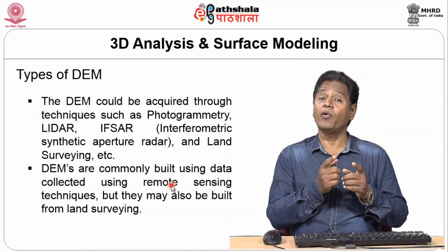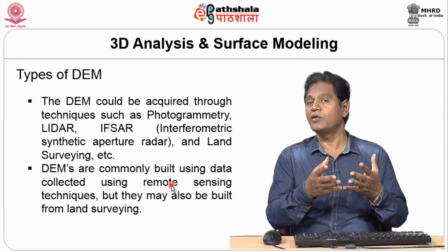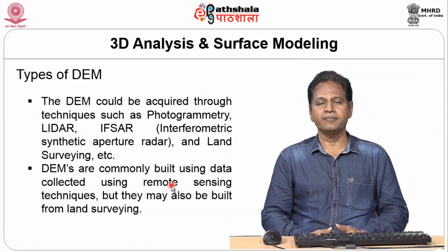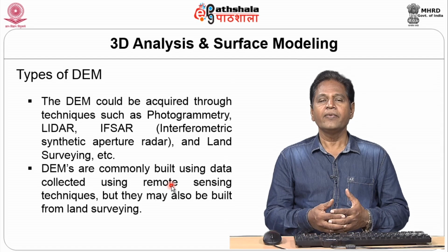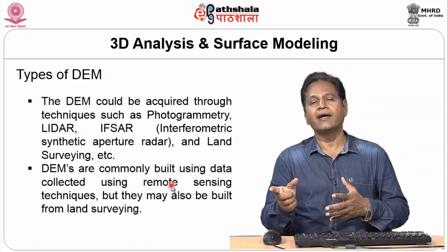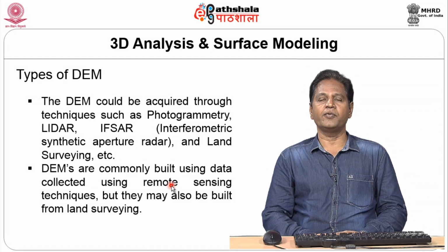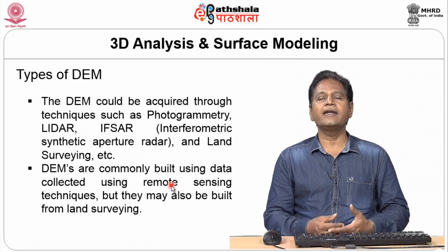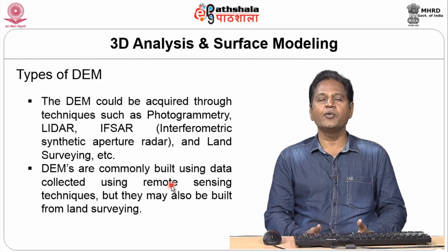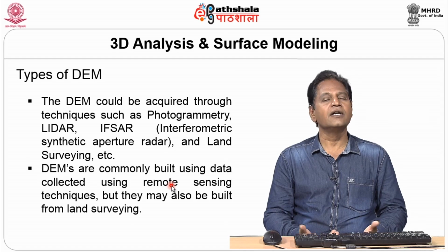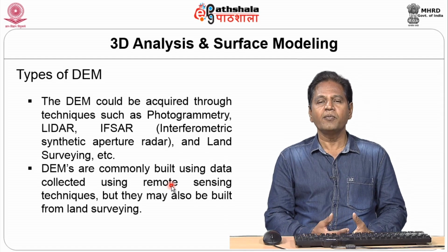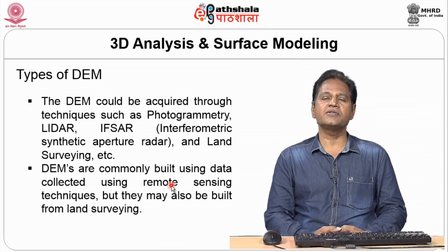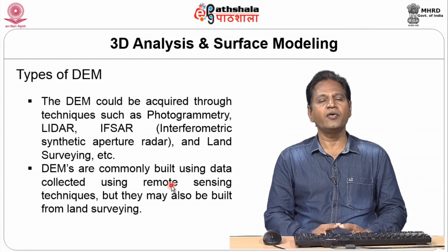that they will be looking at the point which it has passed already, a technology which was not available for a long time. But now it is available. We are able to tilt the same sensor, looking at the same point from a different angle because you have already moved from the first point of view. So, you go to the other point and then get the data. Obviously, as you are looking at the same point from 2 different angles, you will get the depth. So, remote sensing, especially satellite remote sensing, has become a very common input for generation of DEM.